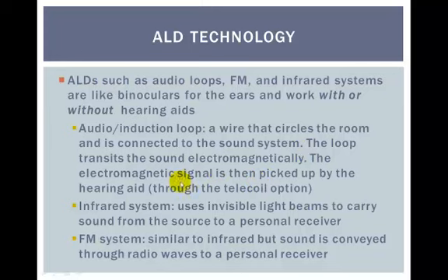But since landlines, as I said, and phone booths are basically becoming obsolete, this loop system is still very beneficial. So if a room, for example, is looped, let's say you're going to a place of worship and it's looped, if you wore hearing aids, you could either set or automatically put them in telecoil mode. That way, when the minister or whoever is leading the group is speaking, that sound is connected through the loop system and will go directly into the individual's hearing aids. So that's the concept of the induction loop.